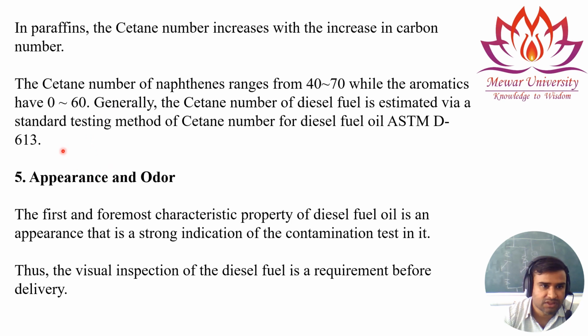Now talking about appearance and odor. The first and most characteristic property of diesel fuel oil is appearance, and that is a strong indication of contamination. If it looks like a different color or a dark color, that means we have more impurities in the diesel.